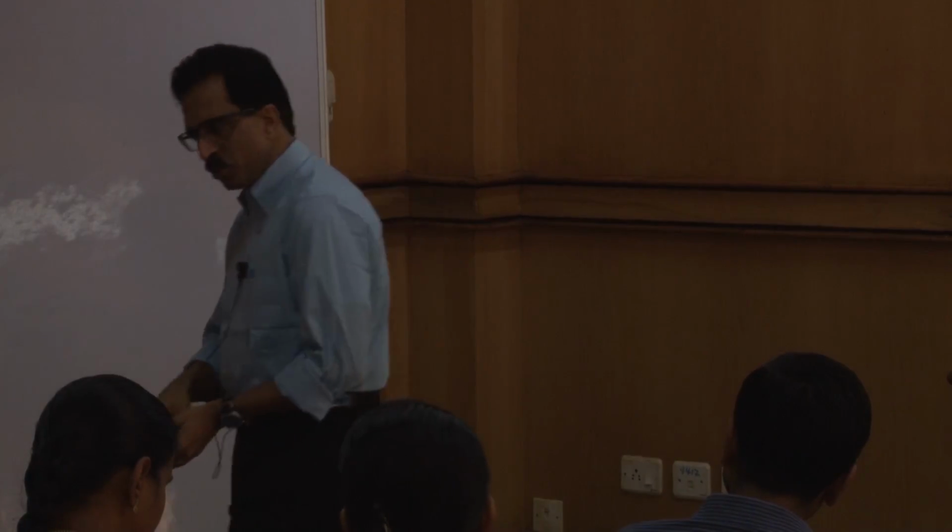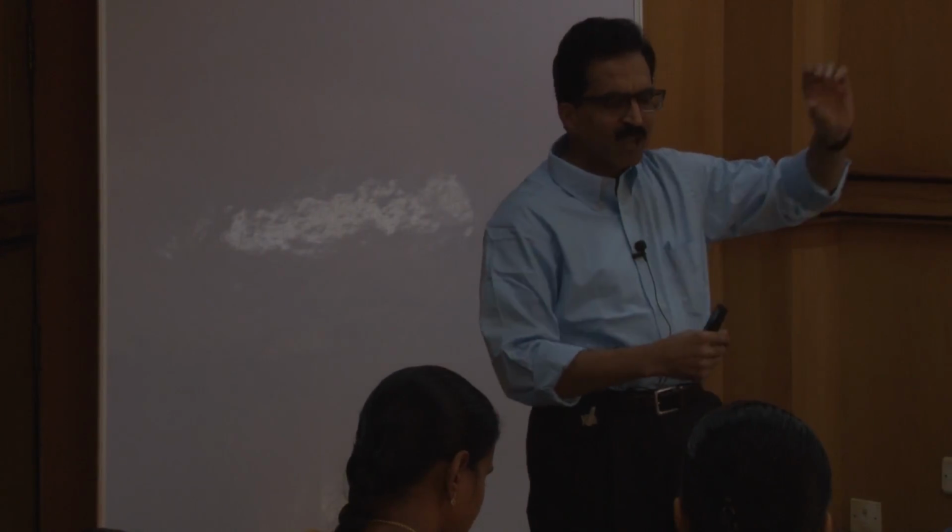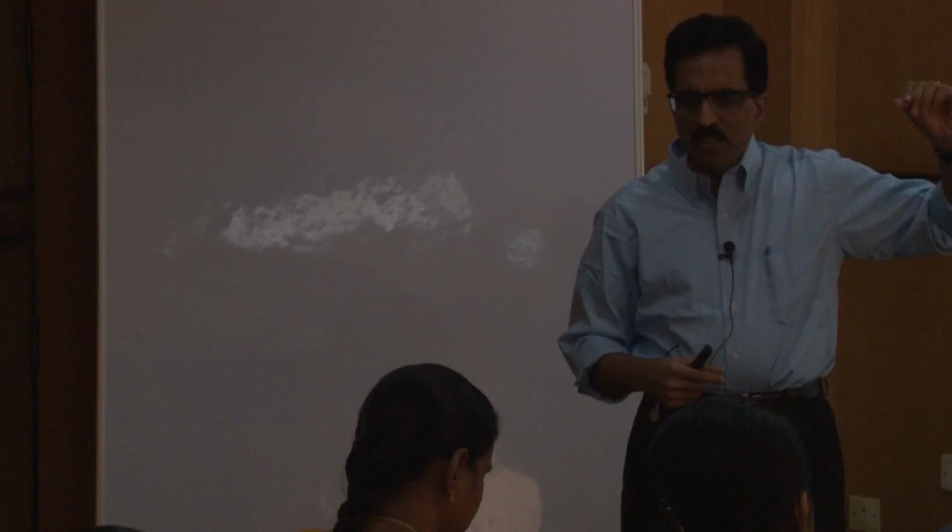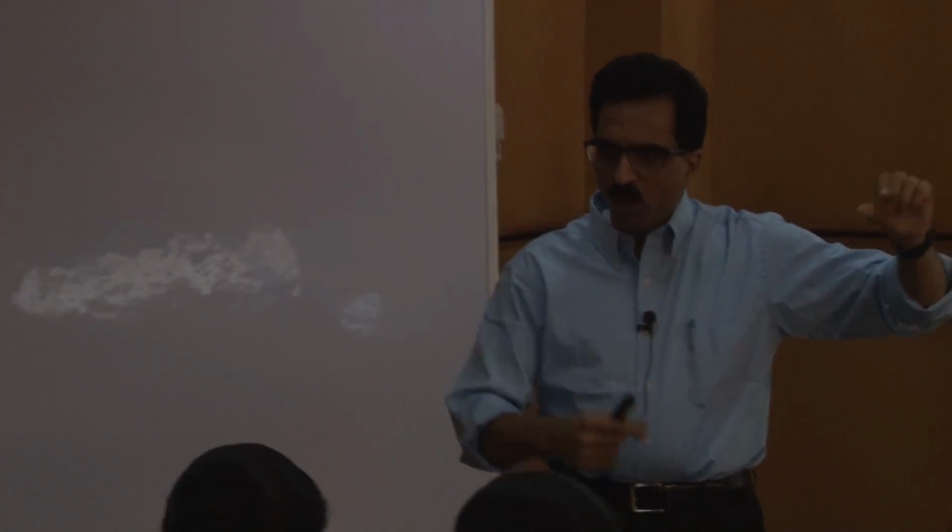There are many other things that you can do. Instead of having the source only at one location somewhere in the middle, you can have perhaps one in the upstream part of the column, one closer to the downstream part, and then these will act as the source, and now your breakthrough curve will be bimodal. Again you can apply moment analysis. You'll have to make some modifications, but these are a whole lot of experiments which I feel offer a lot of insight into solute behavior with very little investment in experimental apparatus.